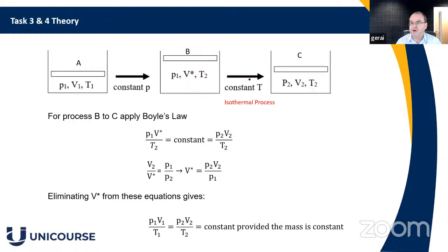So what we're going to do is probably some work on that process. We're going to push this piston down. So what's going to happen as we push the piston down? The volume is going to reduce, and we call that V2. Also, the pressure is going to change. I've put a capital P there, it should be a lower case p. The pressure is going to go up.